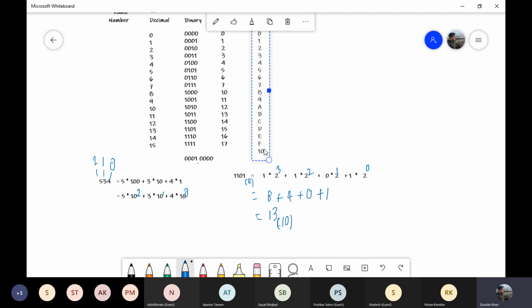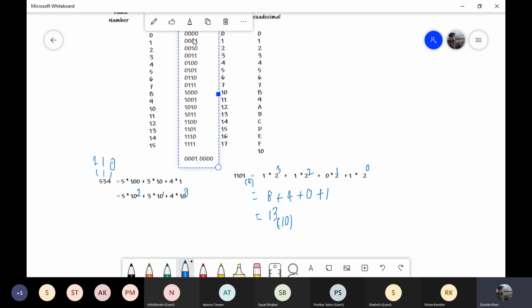Hexadecimal is extremely straightforward because the 16 digits map to 4 bits, which is also called a nibble, and conversion between binary and hexadecimal is straightforward. It is the same case with the octal number system as well. The only change is that instead of all 4 binary bits, you're going to use only 3 binary bits.